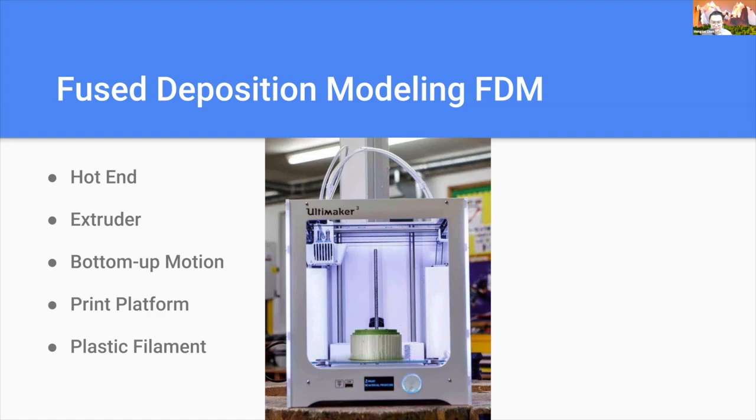So what this 3D printer does is it pushes a very thin strand of plastic we call filament into a very hot, extremely heated mechanism called the hot end and melts that plastic. And when it melts, we deposit it onto a print platform. You can see at the very bottom here. So what happens in this scenario is the print bed would move up to the very bottom, very close to the hot end, right? The plastic will get melted, it gets deposited onto the print bed, and the print bed would move continuously down layer by layer, creating your plastic 3D object.